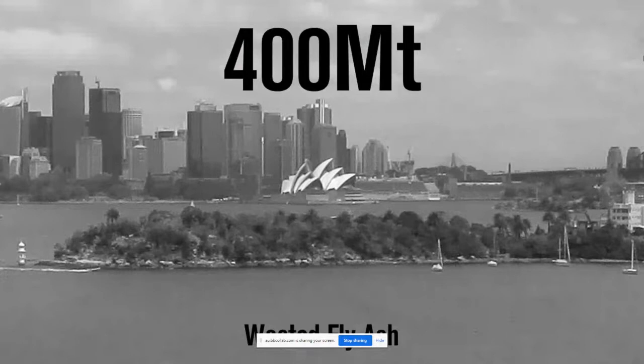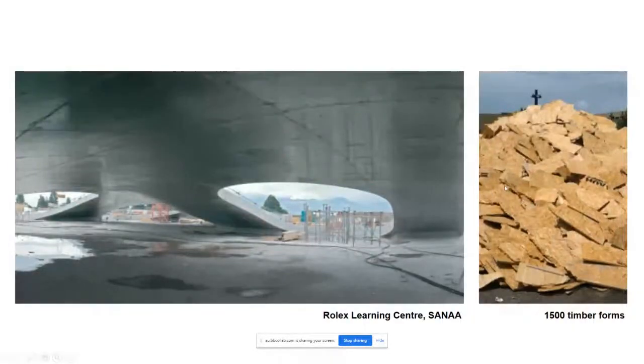It's a dual approach that we're taking at Curvecrete. One is looking at the material itself. We currently have 400 megatons of waste fly ash that we can use for geopolymer low carbon cements that are of equivalent strength to standard Portland cement. The other thing that we're tackling is the formwork required to form the concrete shapes. And here you can see the Rolex Learning Center wasting quite a lot of timber to form this structure.